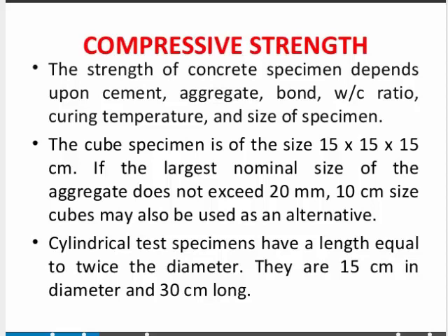So I'll give you an idea of what is basically done to perform the compressive strength test. The concrete is poured in the mold and tamped properly so as not to have any voids. After 24 hours, these molds are removed and test specimens are put into water curing. The top surface of these specimens should be made even and smooth. This is done by putting cement paste and spreading it smoothly over the whole area of the specimen.